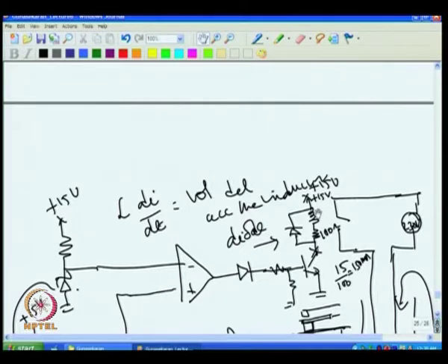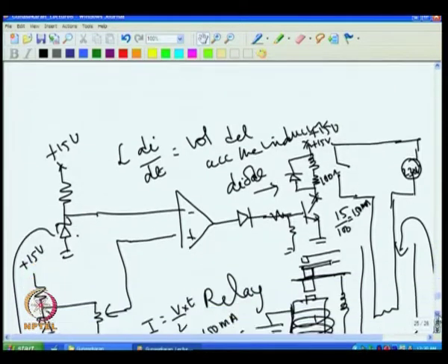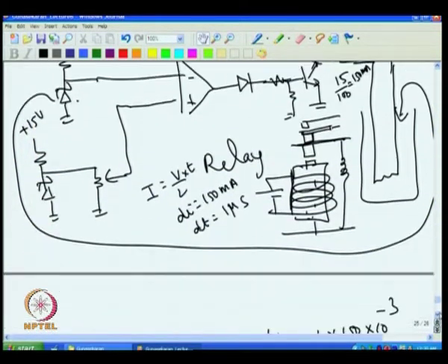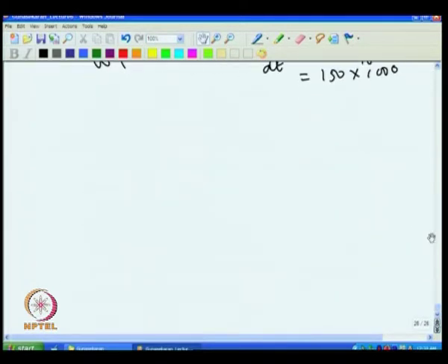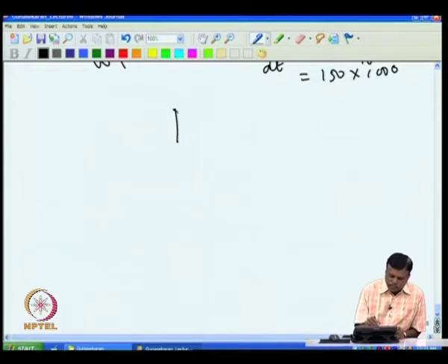So, using a relay also we can make an on off controller. Now, there are very many ways that we can do this. We had shown two ways to control the heater. One is through a relay, that is one case, if I show the output. In one case, what I had done was that the comparator output was there, and I had given it through a Darlington pair.